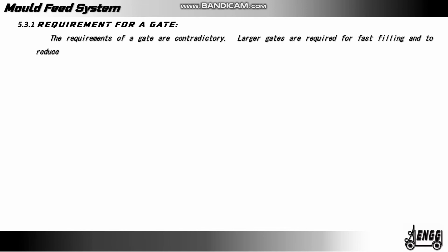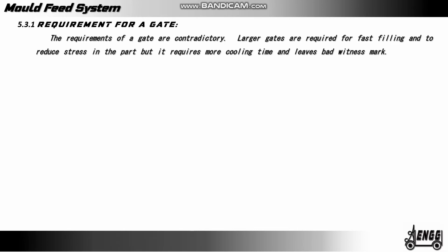Requirement for a gate. The requirements of a gate are contradictory. Larger gates are required for fast filling and to reduce the stress in the part, but they require more cooling time and leave a bad witness mark. A properly designed gate should meet the following requirements.